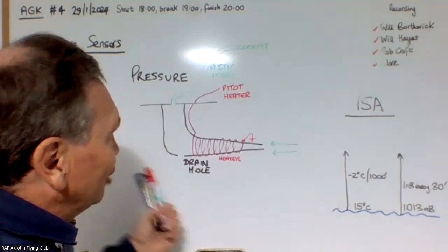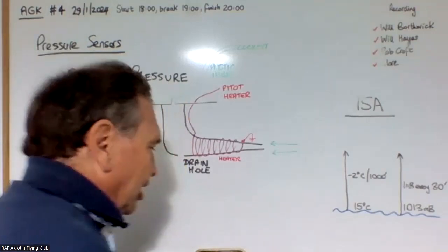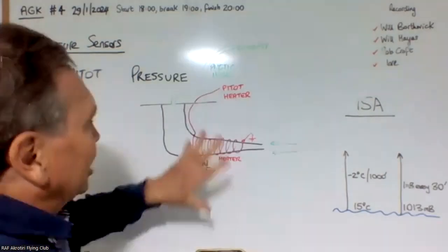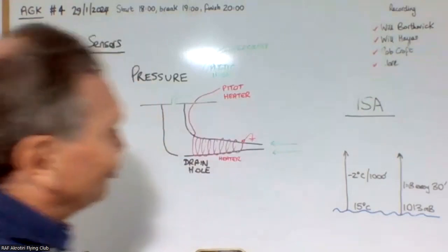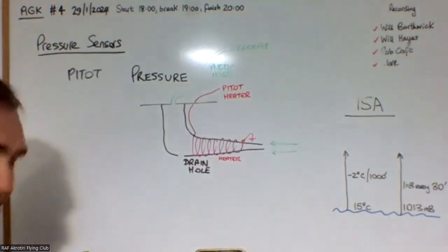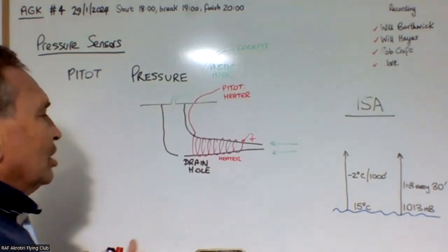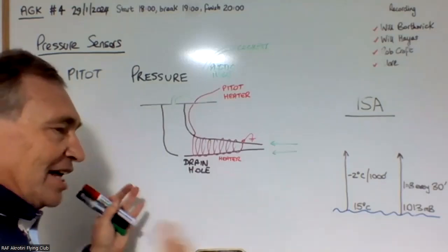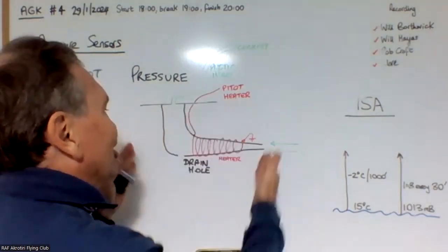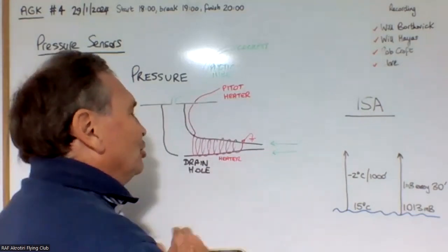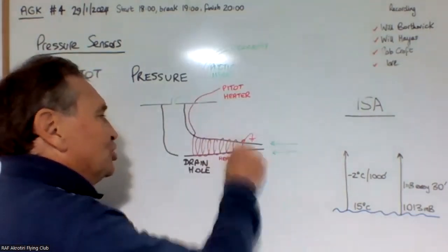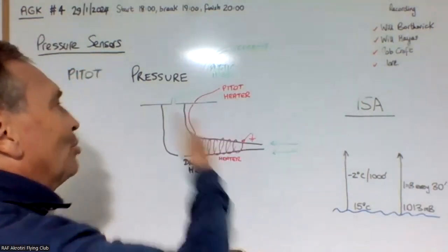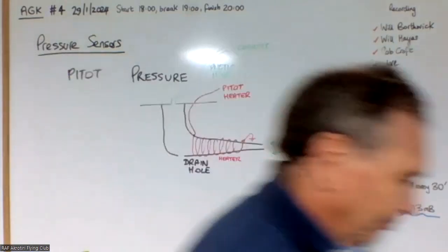So generally, as part of your pre-flight checks, you'll probably find that although it's in your pilot's operating handbook that you should check the pitot heating system before flight, which you always do in the UK, quite often in Cyprus, you'll find that your instructor will tell you that on a good day, when there's no risk of any form of icing ever on your pitot tube, he'll probably say, don't ever bother to check your pitot heater because it consumes so much electricity, we don't want to risk flattening the battery.